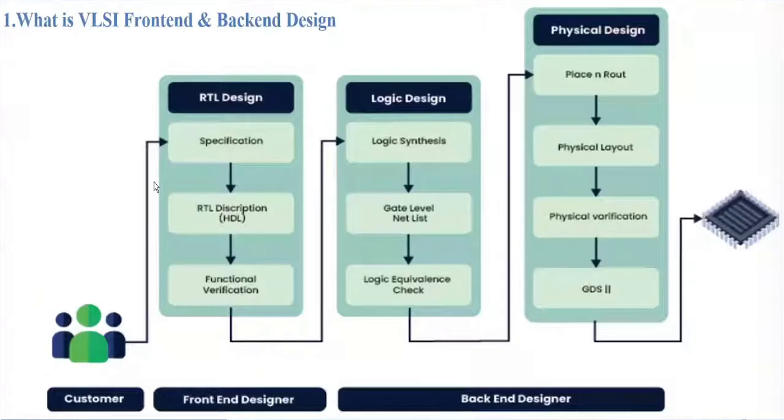White box testing means we are using a concept called assertions. We can include the assertions in the design so that in the beginning only we can find out the bugs, so that we can save our time. When you are using Verilog, after 1,000 time units you can find out the bug by using simulation. But initially itself, we can find out the bug by using assertions.